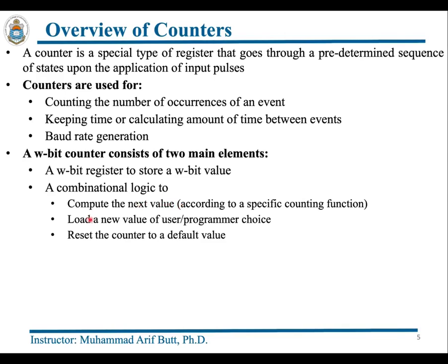The second logic that is required with this register is a load capability. Load capability means loading a new value of the user or programmer's choice. And finally, it should also be able to reset the counter to some default value, which is normally 0.